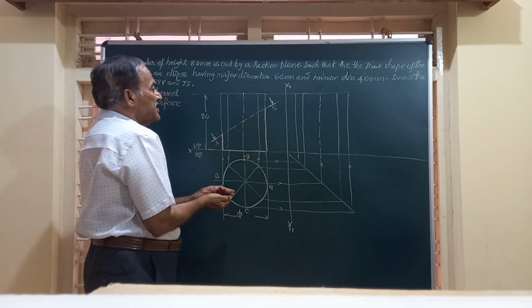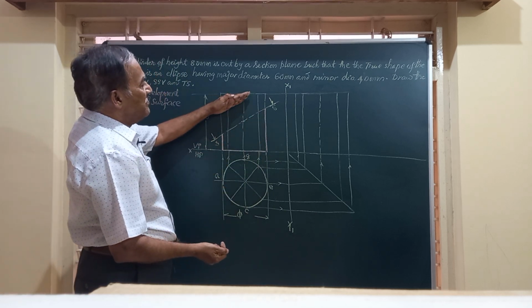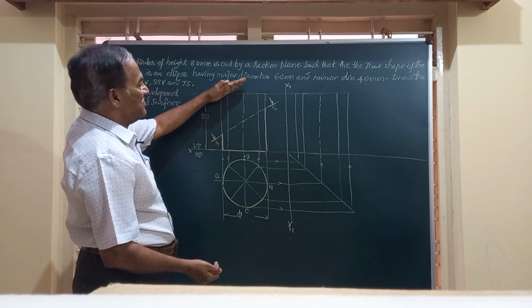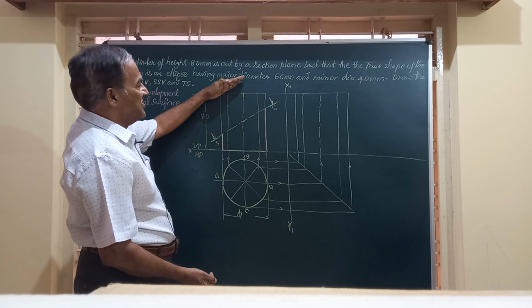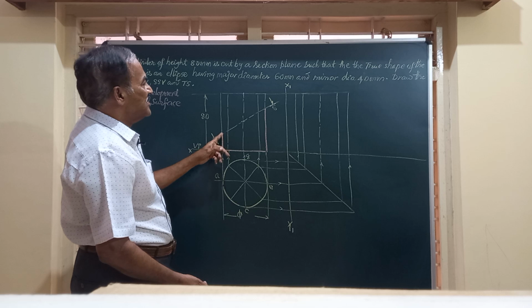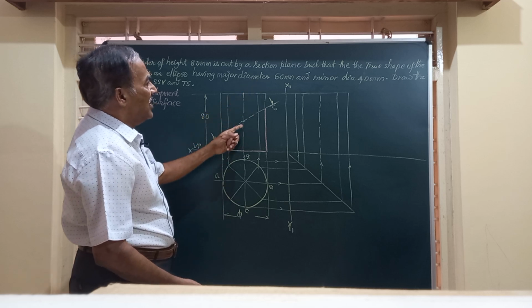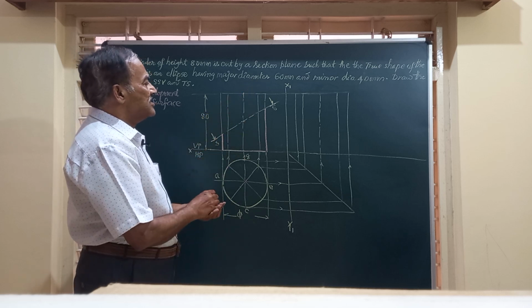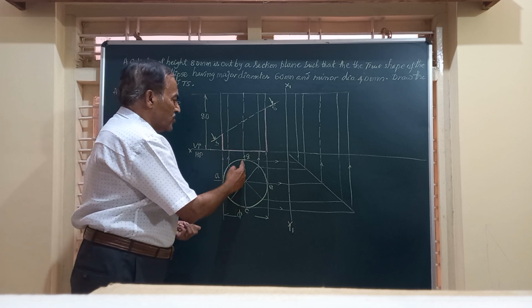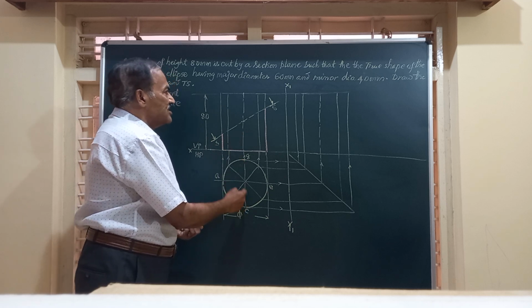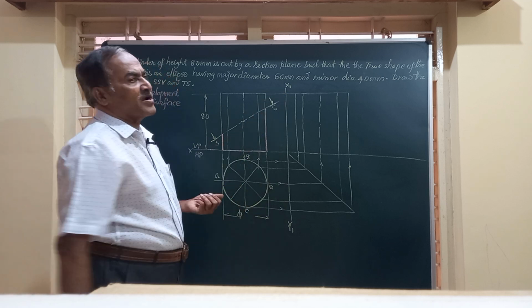So when you are taking the true shape, you are going to hold a mirror parallel to the section plane SS at a convenient distance. And this distance has to be 60 mm. And the other dimension, which is perpendicular to the board, is the dimension CG, which is equal to 40 mm.